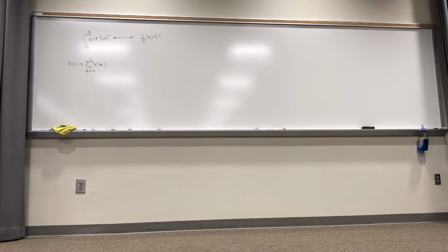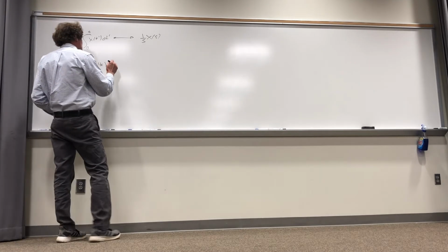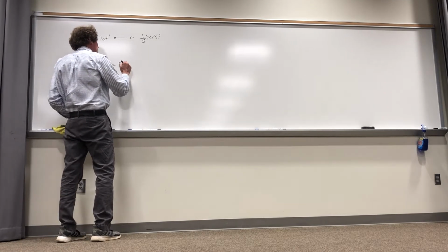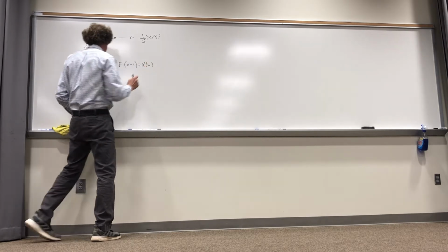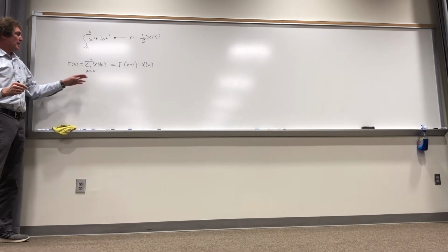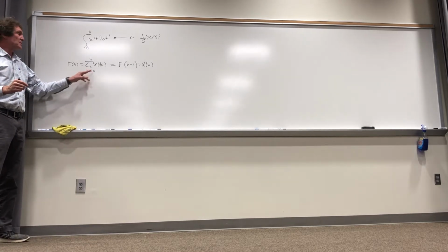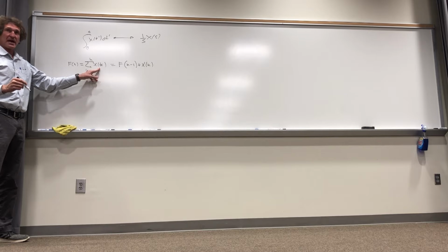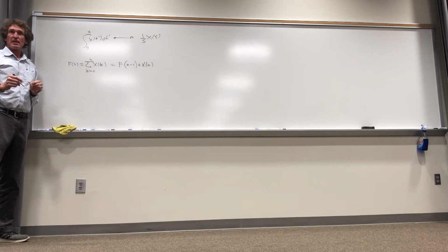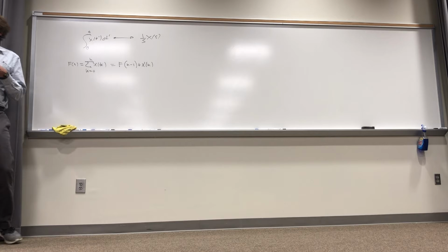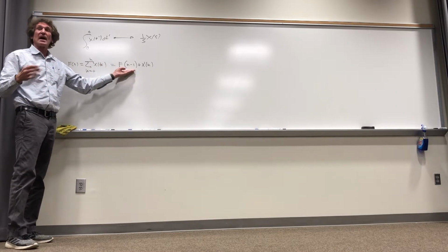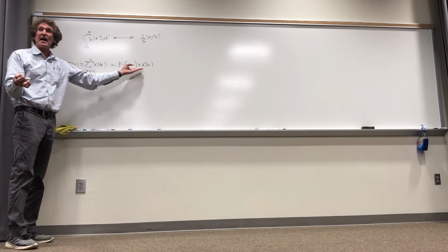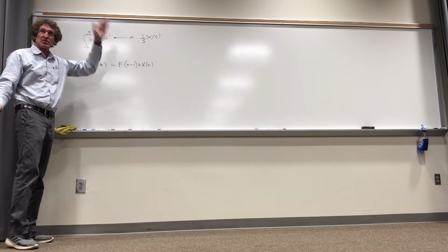Now, if you take a look at this, and we want the Z-transform, this would actually be equal to what? f of n minus 1 plus x of n. Just think about that. If f of n is defined as a summation of all the prior values of x up to n, so you're summing x0, x1, x2, dot, dot, dot, x of n. Therefore, if you sum all those values to n minus 1, you've got every single value except the last one, and you add it. Do you follow me on this? Give me a show of hands if you do.